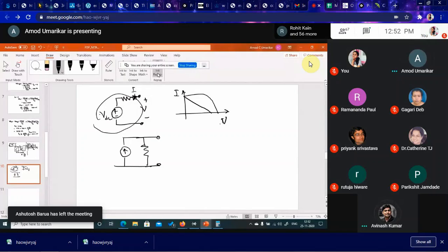Who will control that resistance? That MPPT system. But by using what? Instantaneous voltage and current measurements, and then finding the product and checking whether it is maximum. Yes, correct, you are right. That is done by computer. But in hardware, somebody has to do it.